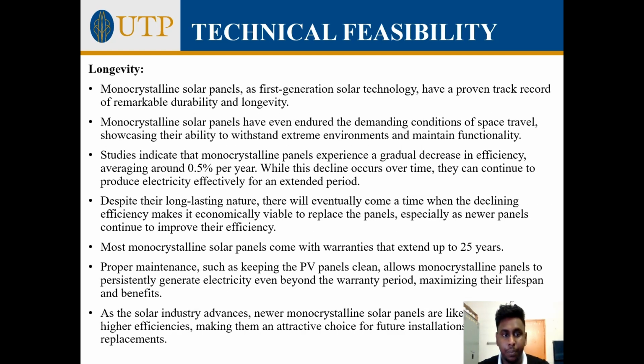Longevity. Monocrystalline solar panels, as first-generation solar technology, have a proven track record of remarkable durability and longevity. Monocrystalline solar panels have even endured the demanding conditions of space travel, showcasing their ability to withstand extreme environments and maintain functionality. Studies indicate that monocrystalline panels experience a gradual decrease in efficiency, averaging around 0.5% per year. While the decline occurs over time, they can continue to produce electricity effectively for an extended period.